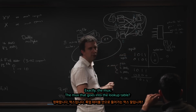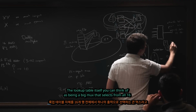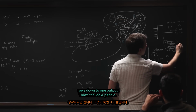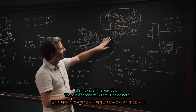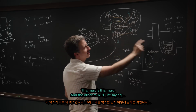Yeah, exactly, the mux. The mux is the core of the lookup table. So the lookup table itself, you can think of as actually being a big mux that selects from all 16 rows down to one output. Yeah, okay, I see. That is the lookup table. But the way you've drawn it here, there's a mux and then a lookup table. It's muxes all the way down. So there is a second mux that is inside here. This mux is this mux.